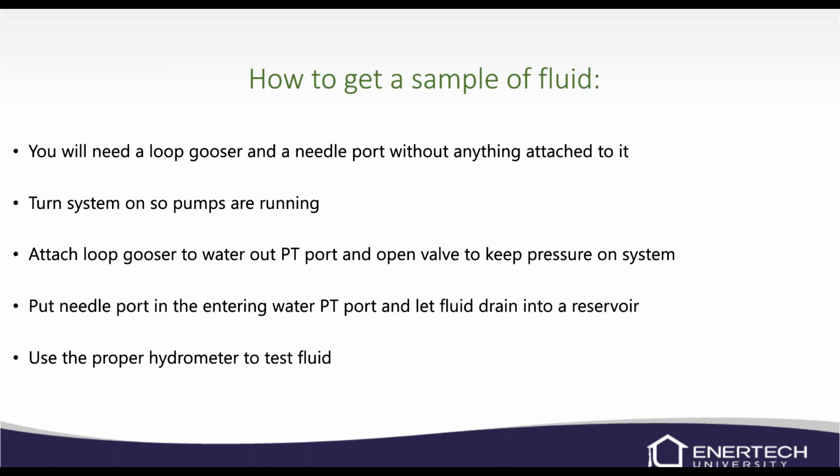After you've got your water, you can check it with a hydrometer, if you're looking at antifreeze levels. You can also use refractometers, which seem to not break as easily as the hydrometers. I don't know if you've used hydrometers in the past, but it's basically a glass tube that they tend to break, so they're hard to keep on your service truck. I probably broke 6 or 8 of them, and I don't even work in the field anymore. So I like to use the refractometers. They're pretty dummy proof. You just put a drop of water on a sight glass and you look through the viewing window and it'll tell you what the level of it is.